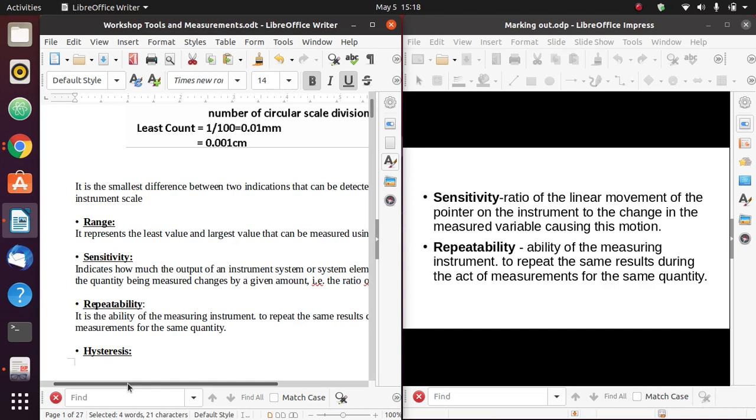That is what I call repeatability. We do this so that we can see how accurate our instrument is. For example, I'll be measuring pressure of 50 bars. I take that measurement once, twice, thrice, 4 times. So if my measuring system, my instrument is accurate, then I will get a value that is the same or close to the same.